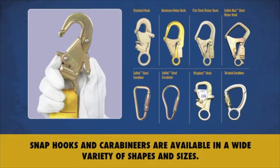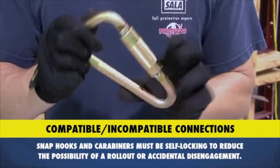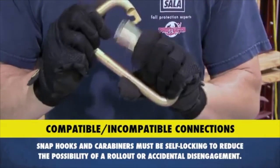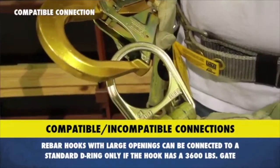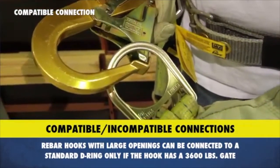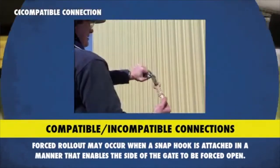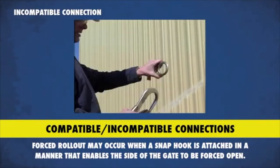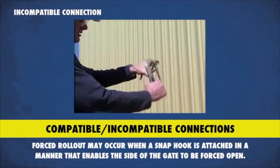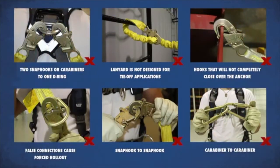These are available in a wide variety of shapes and sizes, but all of them must be self-locking to reduce the possibility of a rollout or accidental disengagement. Although auto-locking snap hooks prevent rollout, they should still be coupled with much larger diameter hardware to prevent forced rollout. Forced rollout may occur when a snap hook is attached in a manner that enables the side of the gate to be forced open. To be safe, you always want to check with the manufacturers to make sure the connections you make are compatible.